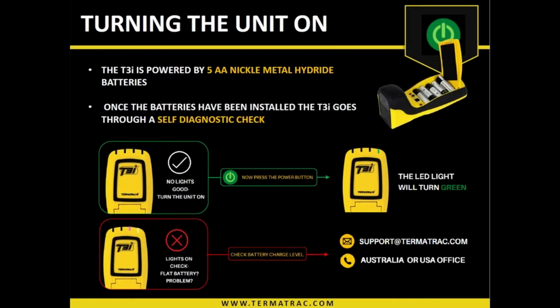If during that process the lights do not stop flickering and/or flashing, or 2 solid lights stay on, that indicates that there is an issue with the device internally. We always recommend replacing the batteries with a new set or a close to fully charged set of batteries to rule out a low voltage scenario. Now, with the new set of batteries, if the lights all go out, that's good.